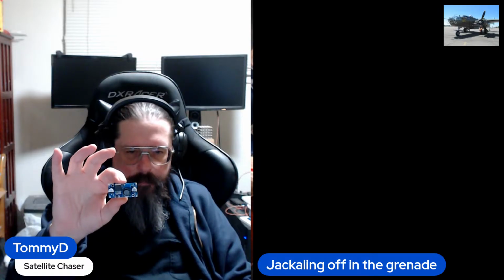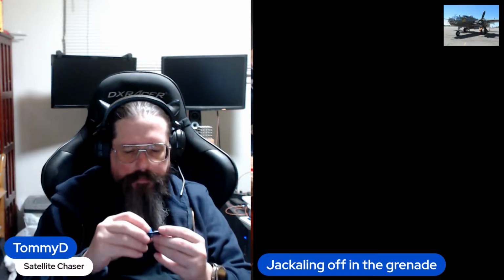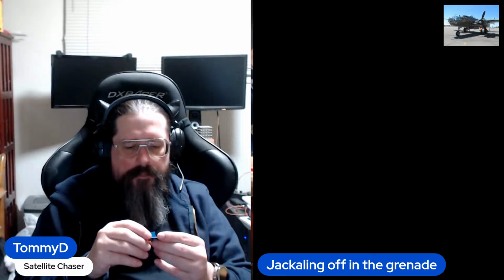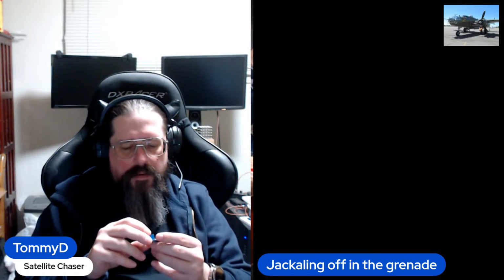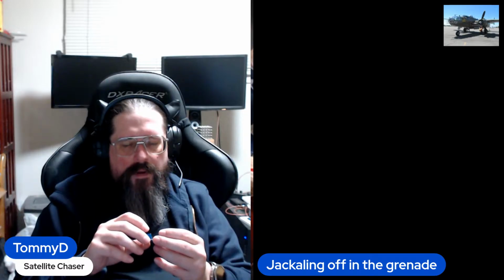Buck converter. You can take this with your 12-volt source and use it as a tap on each of them. The big thing is with your lights, they have to be the common ground. And that's for the data set or the data side. So you can use one of these little modules.